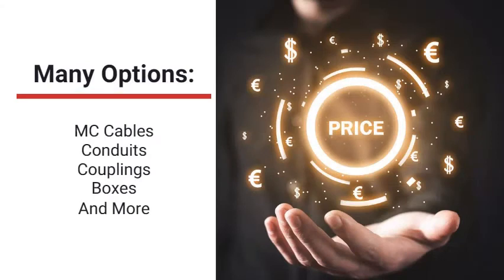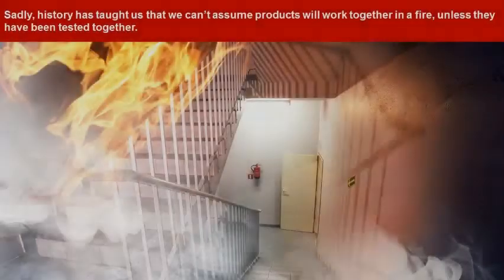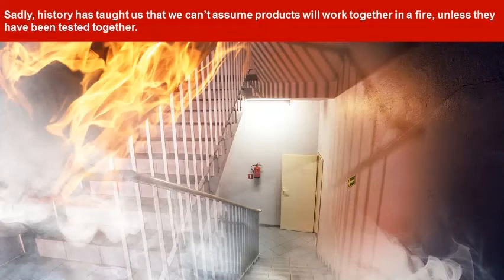As you know, there are many manufacturers and brands of MC cables, conduits, couplings, boxes, etc. available in the market today. For these types of commodity products, price and availability normally determines which is purchased on any given project at any given time. Even with all parties' best intentions, is it practical to think you can always guarantee that the specific brands of conduit and components will be installed for fire-rated applications? Sadly, history has taught us that we can't assume products will work together in a fire unless they have been tested together. That is the essence of Article 728.